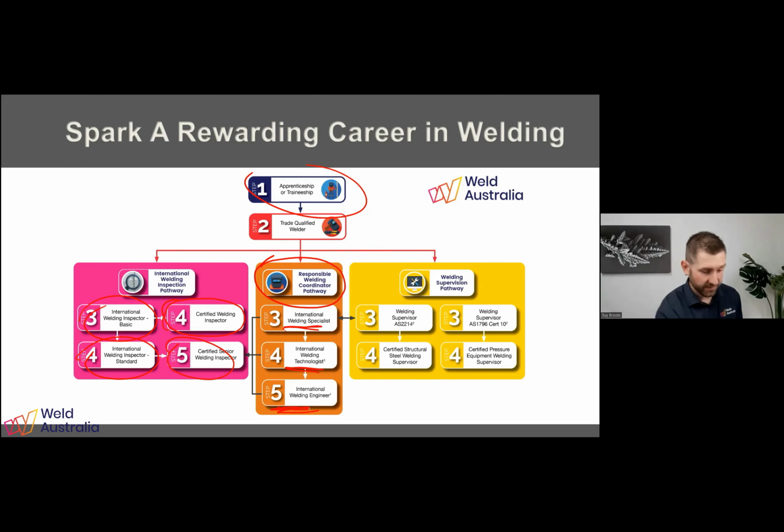The one over to the right of that is your welding supervision pathway. So that's your AS2214 or your AS1796 Certificate 10, which is what I mentioned earlier. Your 2214 is your structural supervisor, basically, and your AS1796 Certificate 10 sits under your boilers and pressure vessels.